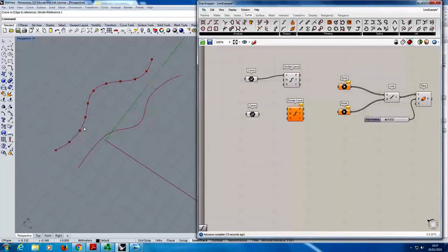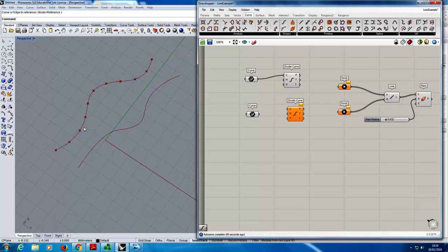And these will actually be evenly spaced, incidentally. So what I was saying before about curve parameters not necessarily being evenly spaced is true, but in this case, this is actually dividing it up based on length rather than parameter space. So you can divide up curves by getting their domain, dividing up that domain, and then pulling out points from that. But doing it that way will mean that your points are not necessarily going to be evenly spaced. I just throw that out there as a warning because that's the kind of thing that if you don't know about it can seriously bite you on the bum.